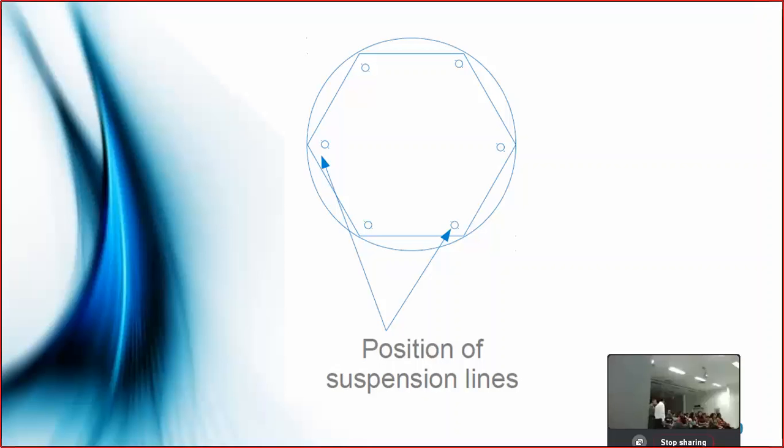There are two most suitable alternatives. Each has its advantages and disadvantages: the hexagonal and the no-line parachute. Let's talk now about the hexagonal. To get the area, just use the drag equation and then calculate the side length of the hexagon.